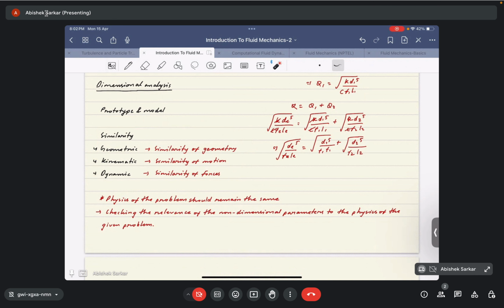Say up to this point, the length of this plate is x. Say we are going to find the velocity profile or flow parameters at a particular location on the plate, so x is the distance of a point from the leading edge of the plate. Now you can clearly see this problem depends on three different parameters. But through dimension analysis you will get to know that all these parameters, if clubbed together, can be represented in terms of a non-dimensional number.